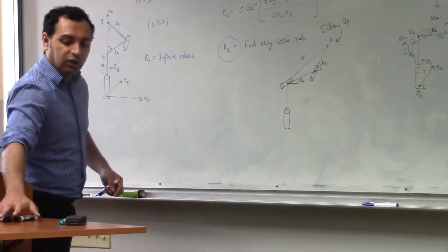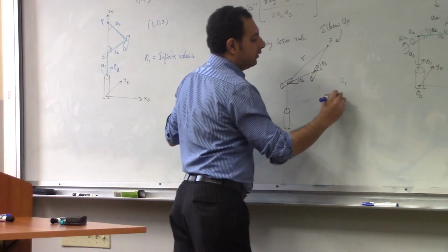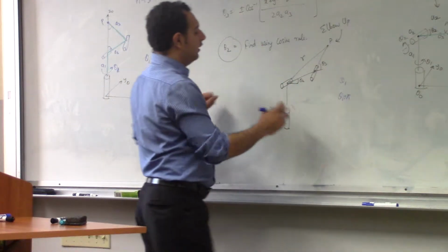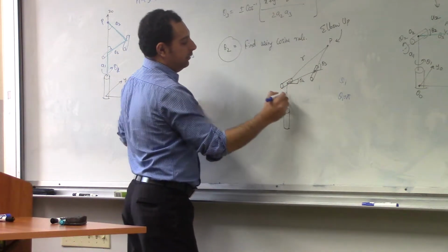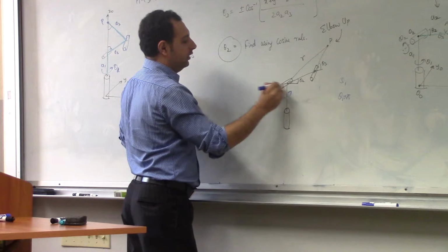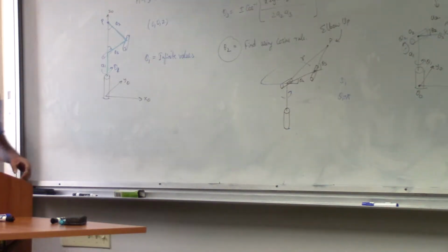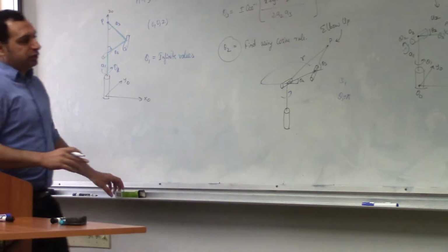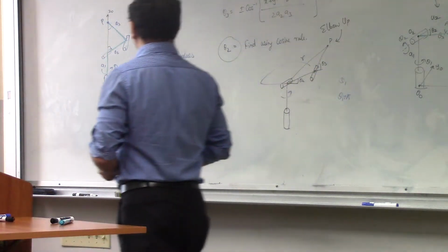So theta 1 will always have two values. It will be theta 1 and theta 1 plus pi, because you can always come to this point by rotating this totally by plus 180. So this will be on this side and then fold over like this. So you have to consider a few more special cases in the case of an articulated manipulator.